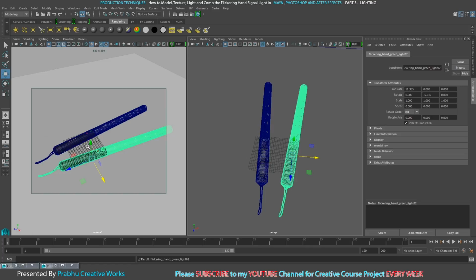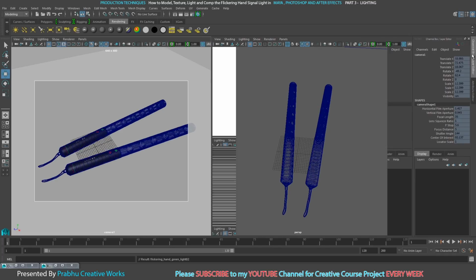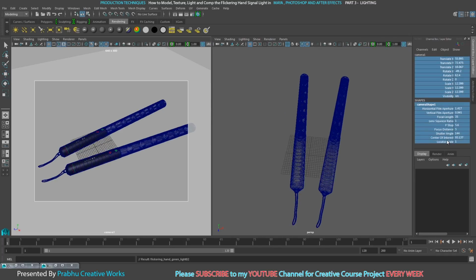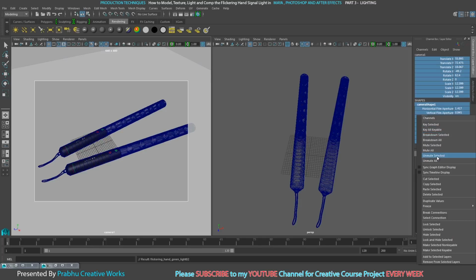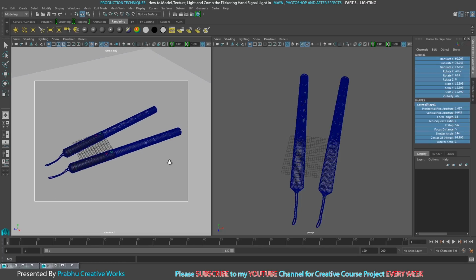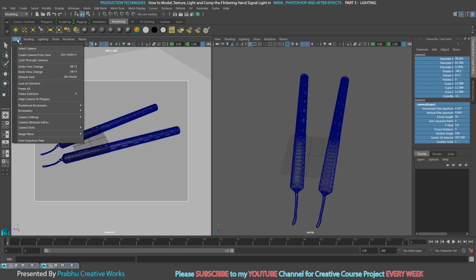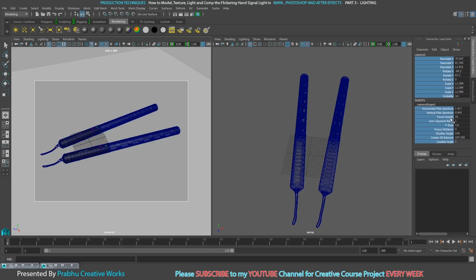So now I want to adjust my camera. See here, it does not show this area. So view, select camera, go to the channel box and layer editor, select all the attributes, right click and choose unlock selected. Now I want to adjust this for my two lights to be visible. So now I lock my camera. View, select camera, select all the values, right click and choose lock selected. That means you cannot move the camera.